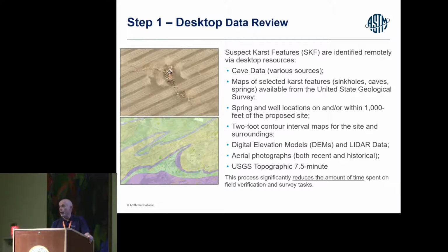a site is karst even if there are no surface features, but it's underlain by karst bedrock. And that's really important, because I've seen many karst surveys where they said the site was not karst because they didn't find a sinkhole. And that's not the case.